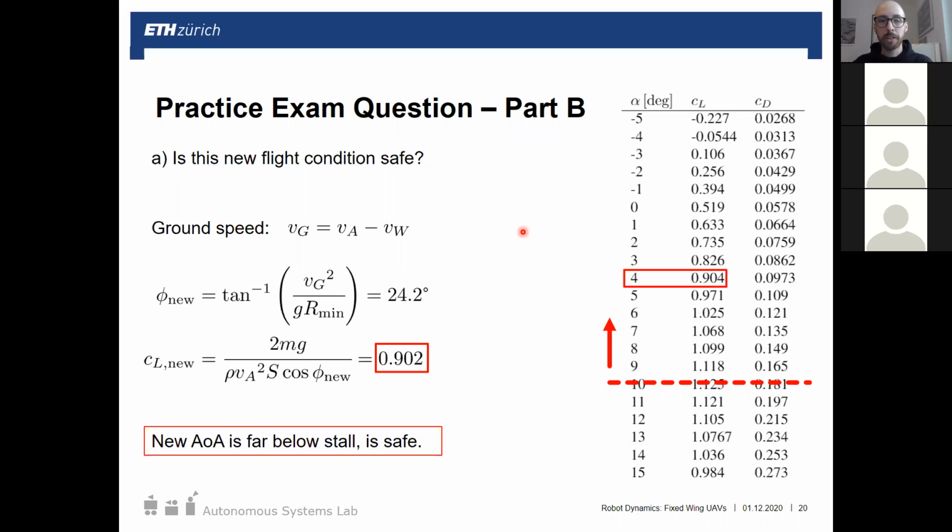So the ground speed decreases when you have headwind, because basically, let's say you're flying and here's a box around where I'm flying, and this box is my air mass. So if the air mass is static, it's not moving, my ground speed is going to be the same as my air speed.